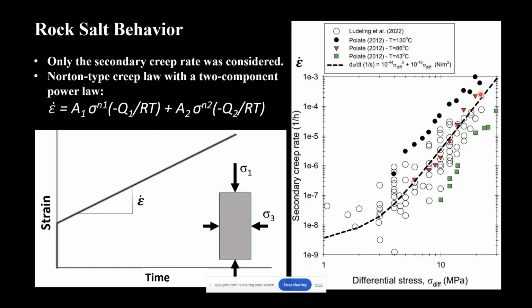And then for this model to have a more realistic behavior of rock salt, I fit a curve that goes in the middle of this range, right? And this term here is governed by this expression, which has a stress exponent of 5.